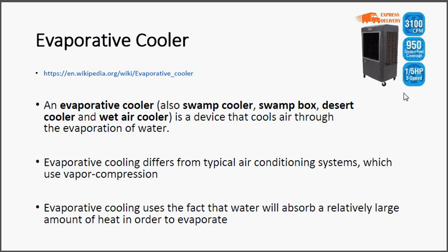Yeah? So you just literally evaporate the water, and you can do this by forcing air over the water. And so the hot air from within the room, the building, wherever you are, which is blown over the water evaporates, and in turn blows cool air out. Obviously, it doesn't work in wet climates, but it's ideally suited for dry climates.